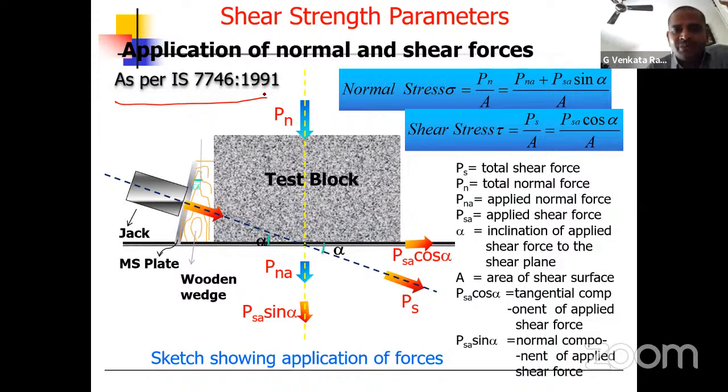First, in soil mechanics also, if you want to calculate the direct shear test, we have to perform a minimum of 3 tests. How to perform? First, there is a need for one sigma 1 and corresponding shear, sigma 2 and corresponding shear test, and sigma 3 and the corresponding shear stress.